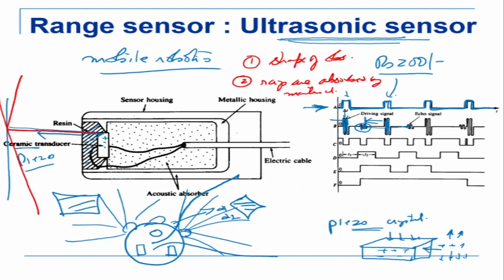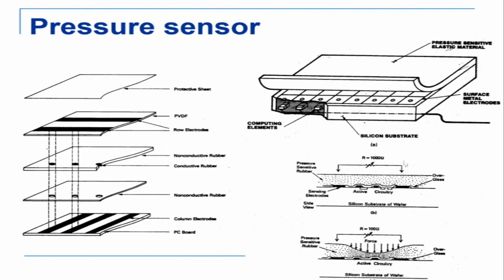Now these are proximity sensors. The other kind of sensors are pressure sensors, which are used on the fingertips of robots for sensing, for example, haptics. Haptics is one application of this kind of pressure sensor. How they work is very simple. You have a row of electrodes as shown here. There is one layer of rubber with rows of electrodes, and another with a cross row of electrodes.